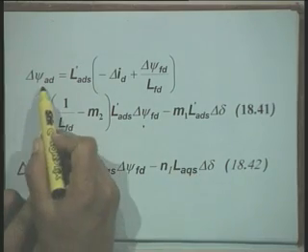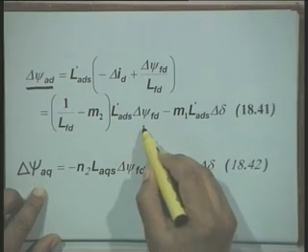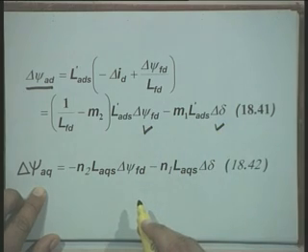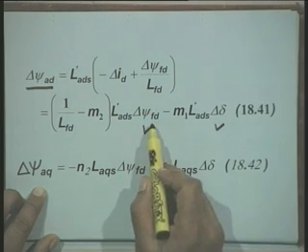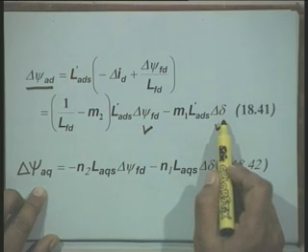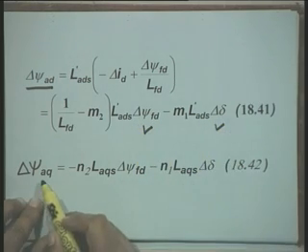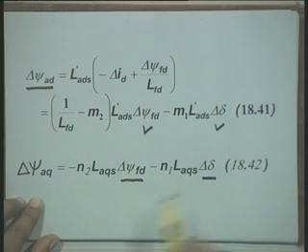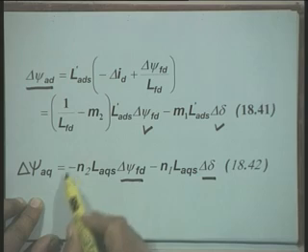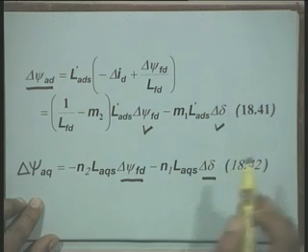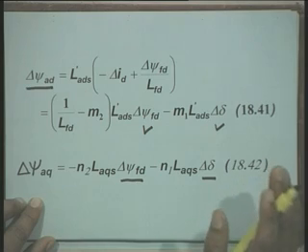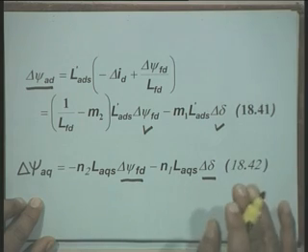For example, delta psi AD can be written in terms of the incremental changes in the state variables, that is delta psi FD and delta delta. Delta psi AQ can again be written in terms of these state variables, and the coefficients of these terms are again functions of the machine parameters, system parameters and operating condition.